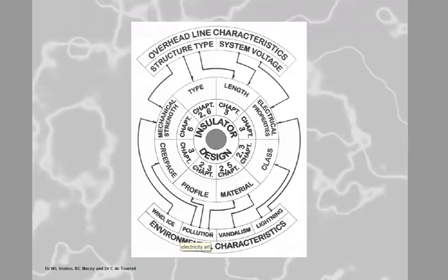Or the pollution deposits on it, and it turns into a hydrophobic surface, because low molecular weight silicones migrate to the surface and encapsulate the pollution particles, making all these little methyl fingers stand out, creating a duck's back hydrophobic surface. So now it can't dissolve and form an electrolyte. Well, where are the currents? You got it.